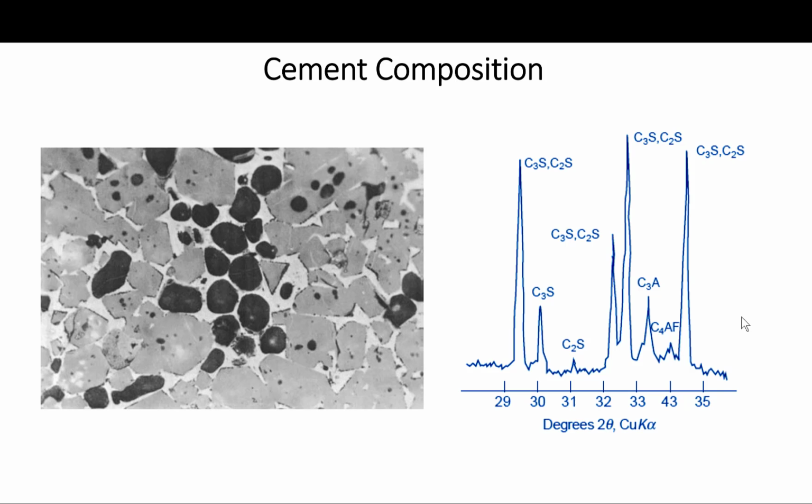It affects its properties. Another factor is the inclusions of other elements within the cement phases. For example, these phases are never, as I said, present in the pure form without any inclusions. For C₃S, the impure phase is alite, as I mentioned earlier. For C₂S, the impure phase is a common phase called belite. And other phases, of course, have the same.